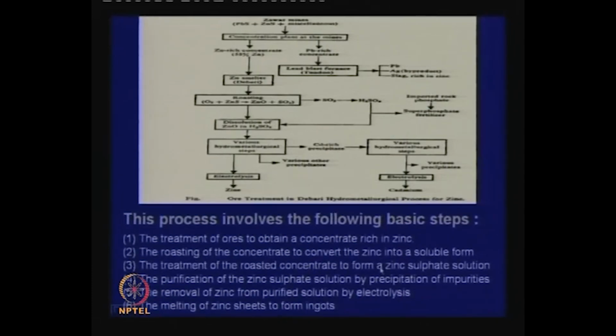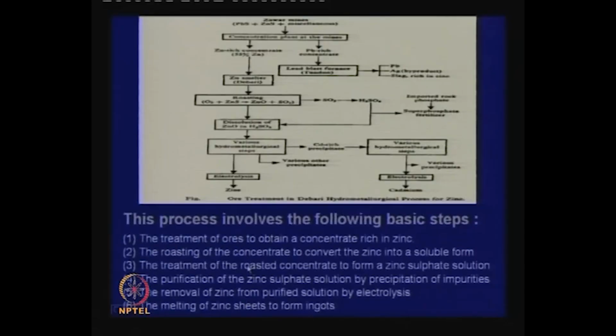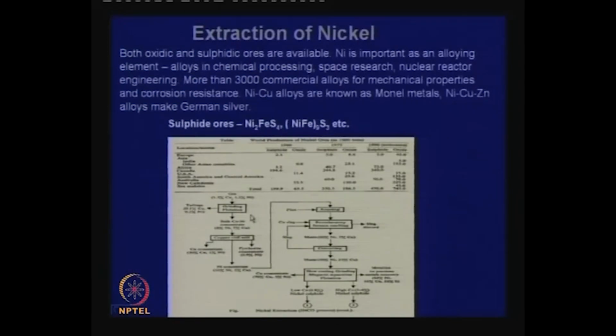Then there is a zinc sulphate solution which is purified, and from that zinc is obtained by electrolysis. This zinc is very, very pure, better than 99.99%, more than what we require for galvanizing, but we have to have pure solution. That is why we get very pure zinc, whether we like it or not. The concentrates also go to another place near Chittor in Rajasthan, where the imperial smelting process operates.